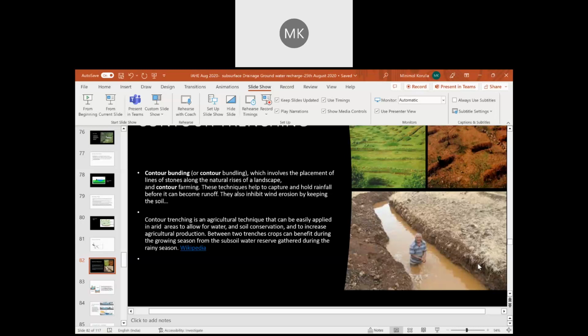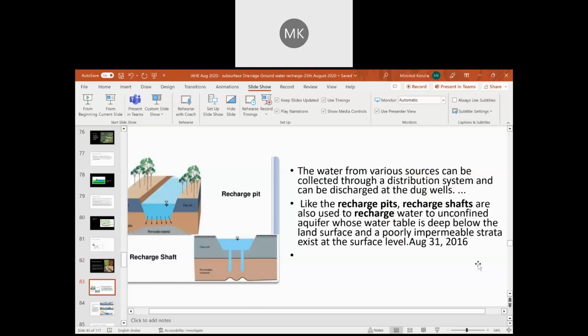Okay, so as I mentioned, the seepage lines need to be decided, and for that different types of software are nowadays available. If we can select one of the software, and accordingly decide what the in-plane flow direction is, that will help the designer to really understand precisely how we have to give the drain, at what inclination, with what capacity and in what direction. Okay, so the determination of the seepage line is important.